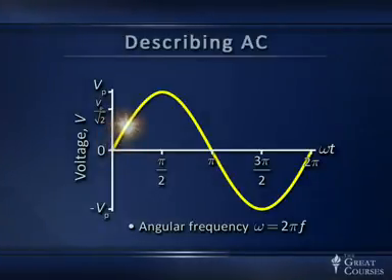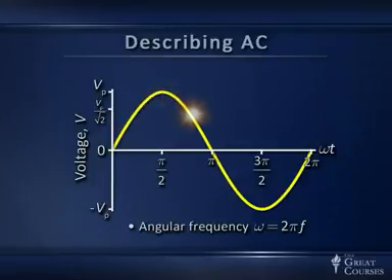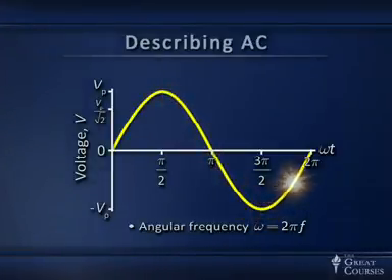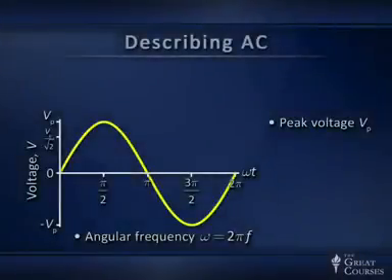The curve is sinusoidal in shape, and the reason for that, at least in the context of AC power, as we've seen before in talking about how electric generators work, is that electric generators are coils of wire spinning in magnetic fields. We're changing the magnetic flux by changing the angle and therefore changing the cosine of the angle, which determines the flux. The rate of change of cosine is sine, and we get sinusoidal waveforms. So sine wave AC is a natural result of generators produced by rotating coils in magnetic fields. So I've marked several other points on here.